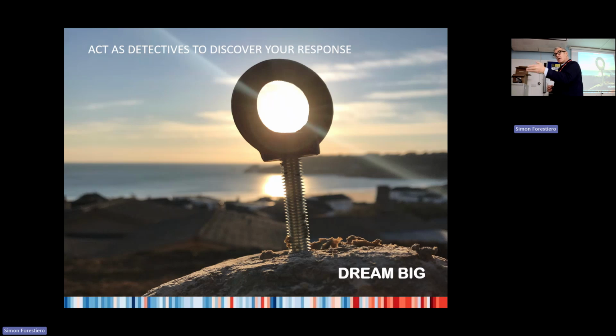You wouldn't go out there, would you? But what you can do, like they do in Switzerland, is the winter garden. They do single glazing on the outside, really easy to open, but you get a terrace that's protected with a bit of air leakage, and you can control the vents. Now, I'm not trying to push you all down that way, but it saves money because you don't have to do air conditioning. Yes, absolutely. There are loads of different options, and it's just that there's so much to look at.